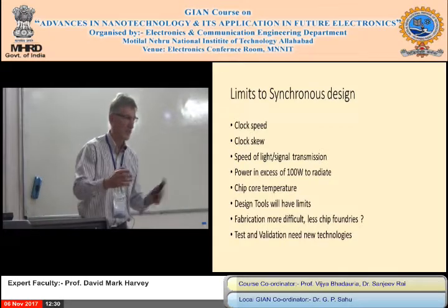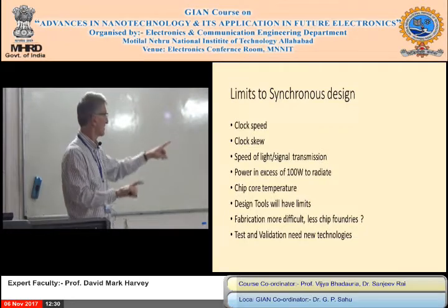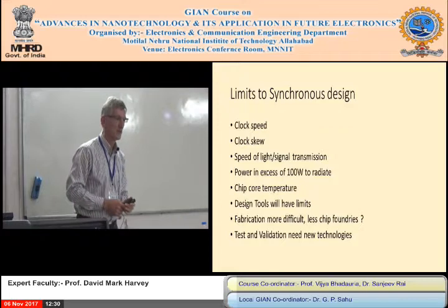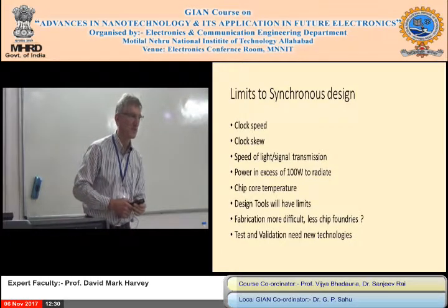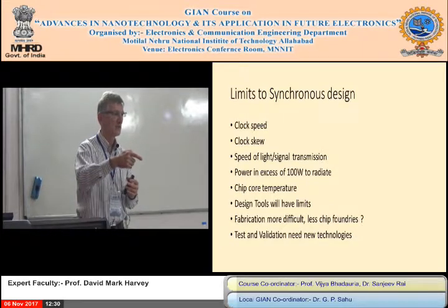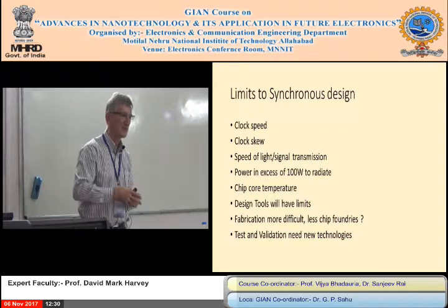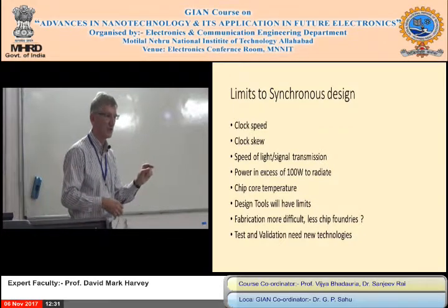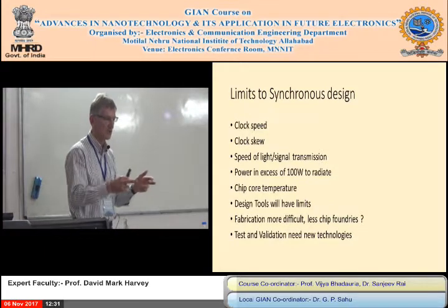How long is it going to take then to go on the circuit a tenth of that? Well, it's going to be a tenth of a nanosecond. So 100 picoseconds. So the transistors switch in at 100 gigahertz, I think that's about 10 picoseconds. You're going through 10 transistors, the signal will arrive before it's gone through the transistors, or vice versa, depending on the connection. So connection routing will become very, very important. You don't keep it short. And again, that's the same for any circuit, synchronous or asynchronous. You need to keep the connection short.